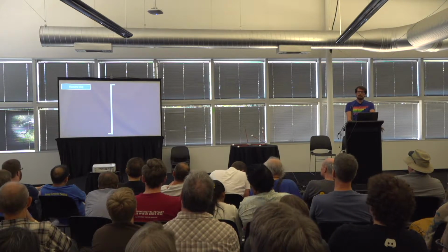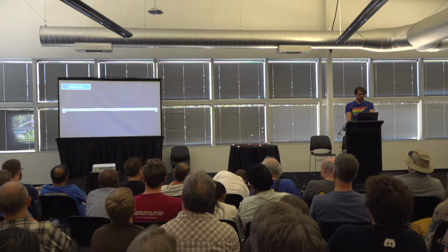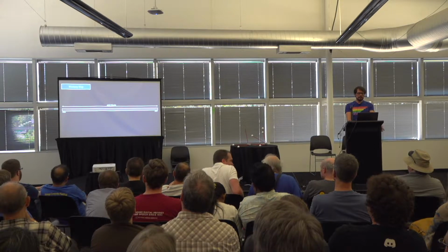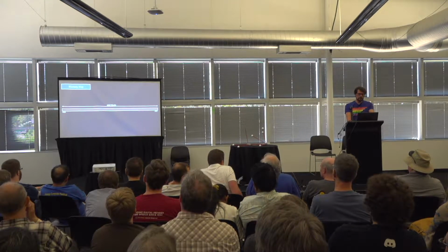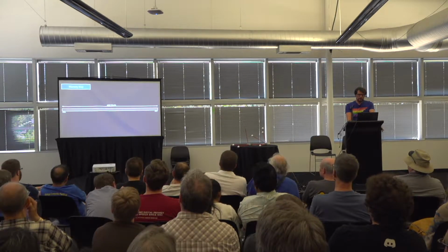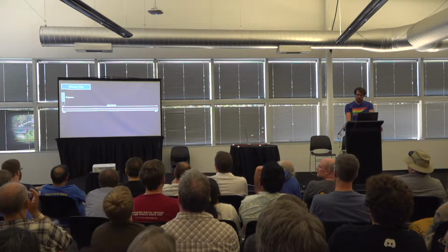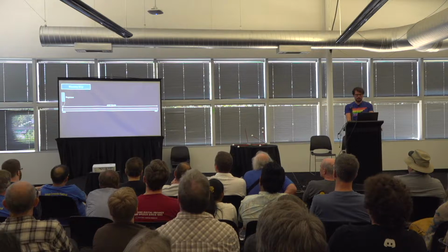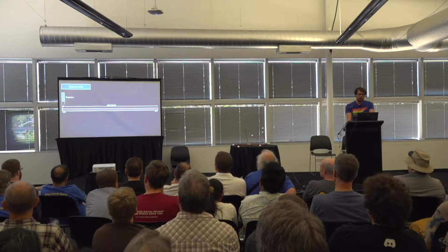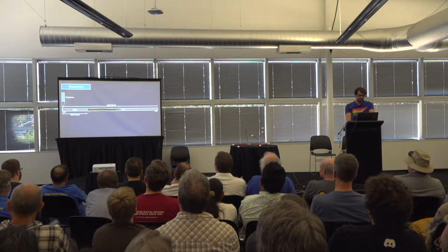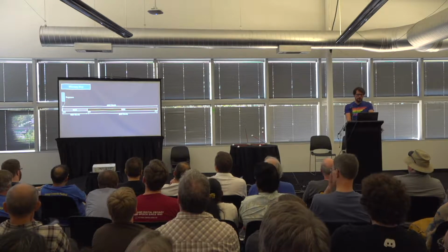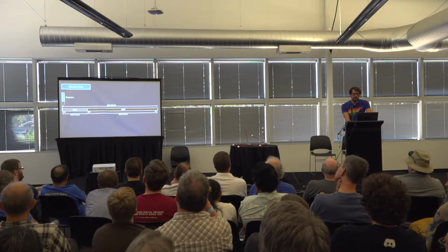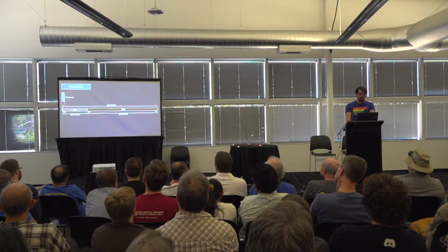Let's look at the memory map more closely. Memory is 4096 words and goes from 000 to FFF. The registers are located at the very bottom of memory. Including these, there are 1024 words of RAM, random access memory, and 3K words of ROM, read-only memory. The AGC was originally architected to only have this little RAM and ROM, but there's actually more.